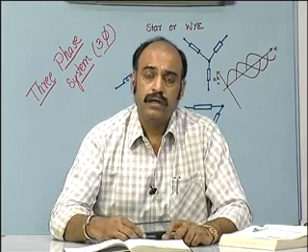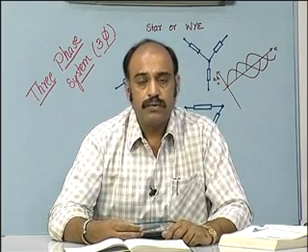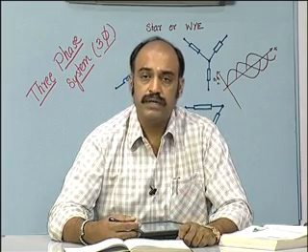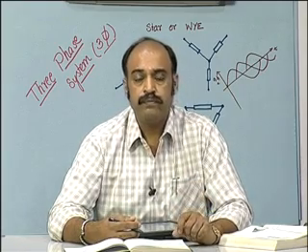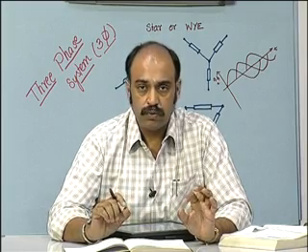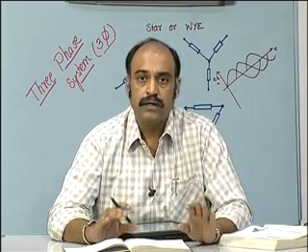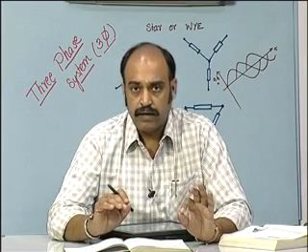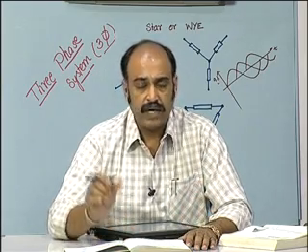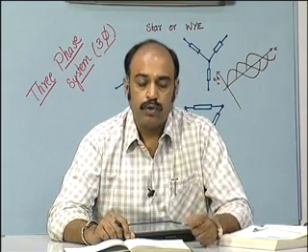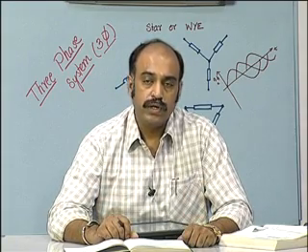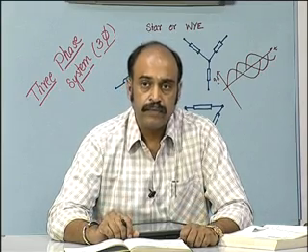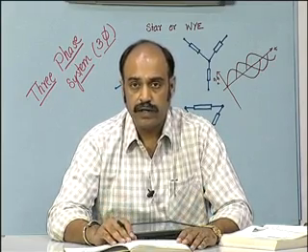And then we discussed the measurement of power. The best method to measure the power in the three-phase circuit is by means of an oscilloscope. You measure the voltage and the current together using a voltage probe and a current probe, the line voltage and the line current, and then compute root 3 E_L I_L cos φ, and the phase difference can be obtained from the voltage and the current waveforms that can be seen on the oscilloscope. That would give you the best method. It is independent of whatever the power factor is.